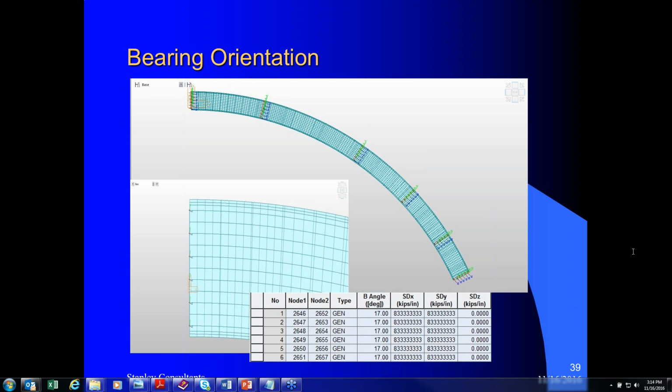We did not study that because, as I mentioned, we used the grid model for the superstructure design. We did not use Midas for that, so I couldn't answer that question. We used Midas basically for the lateral response, the total lateral response of the system, including the stiffnesses of the piers and the soil springs.